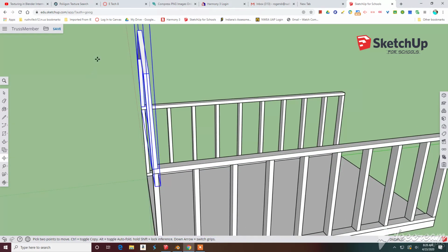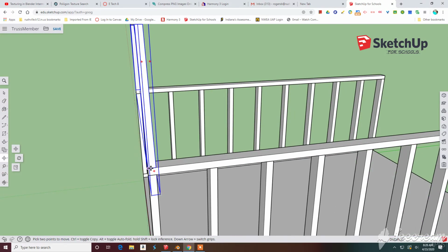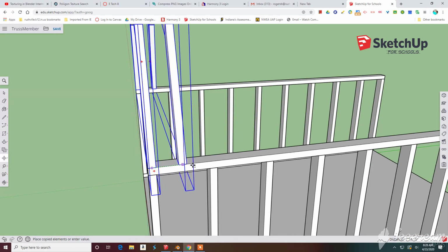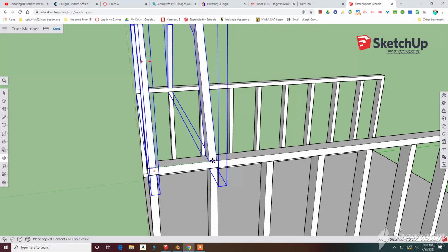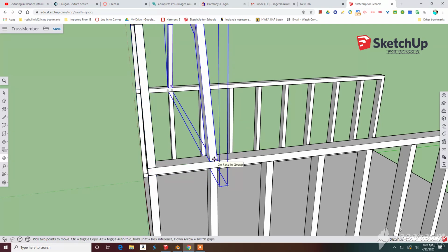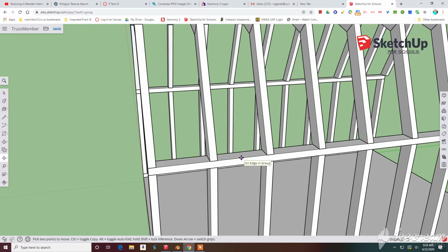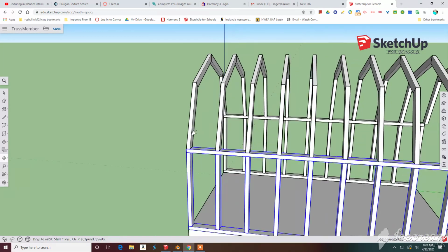The way I do that is just like we did with the wall systems. I'm going to use my move tool here. I'm going to select the center of this particular gambrel, and use the control key again to tell the computer I want to copy. Now I'm going to move this over exactly 16 inches. All right, and then I'm going to use the asterisk once again, and we're going to type in 9. What that's going to tell it is that I want 9 additional copies here.